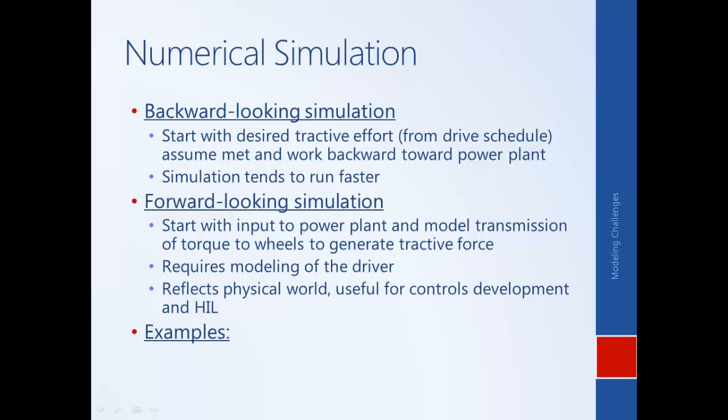Some examples of commonly used simulations for electric vehicles and hybrid electric vehicles are the package which used to be called PSAT, which is now Autonomie, which was generated by Argonne National Labs, which uses a forward-looking structure to the simulation. There's also the ADVISOR simulation, which is generated by another national lab, NREL, the National Renewable Energy Laboratory, and it has aspects of backward-looking and forward-looking simulation, so we'll term it a hybrid sort of architecture.